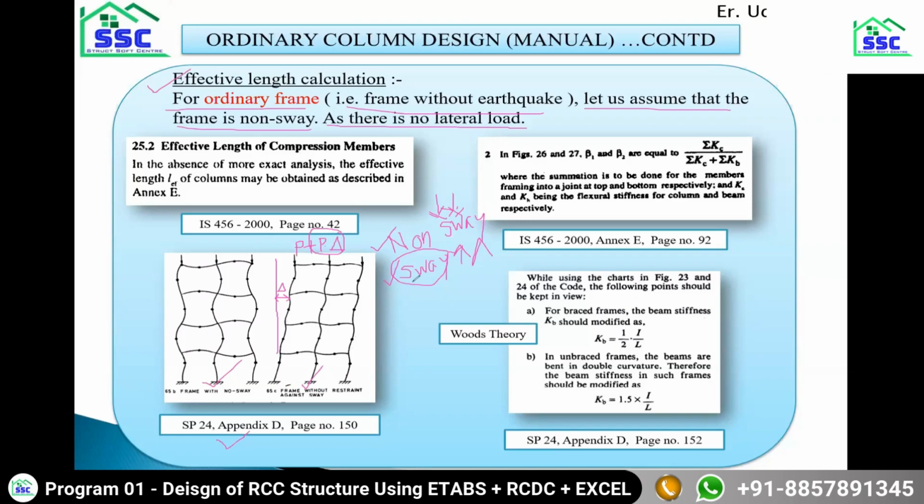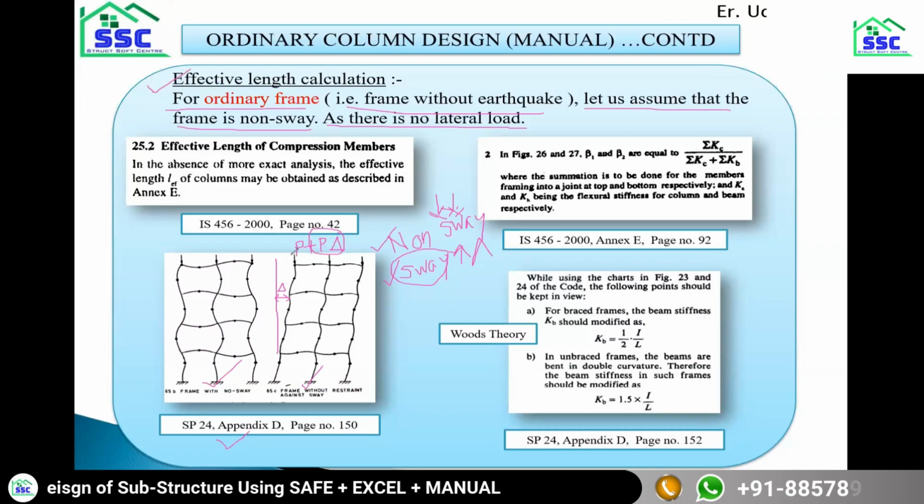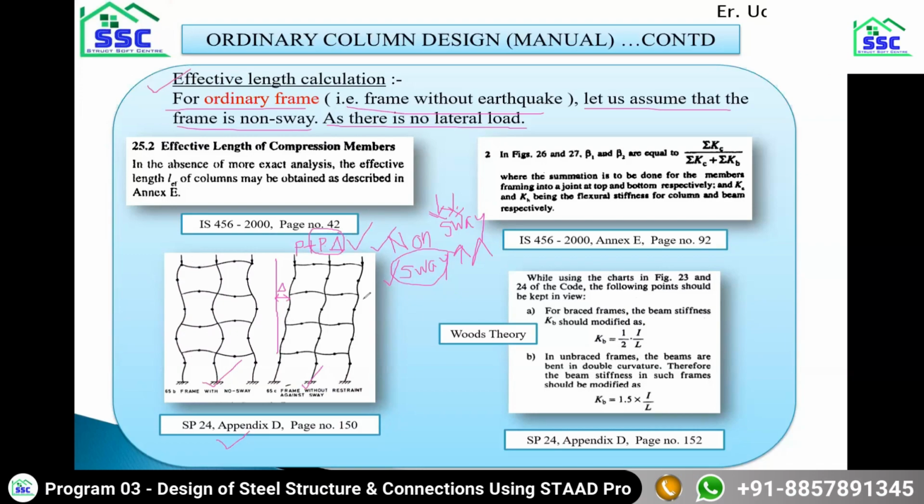When it is a sway frame, it is mandatory for you to consider the effect of this delta. But if that delta itself is negligible, you can ignore that additional bending moment of P delta and perform your design considering it as non-sway. I hope you got the concept of sway and non-sway.